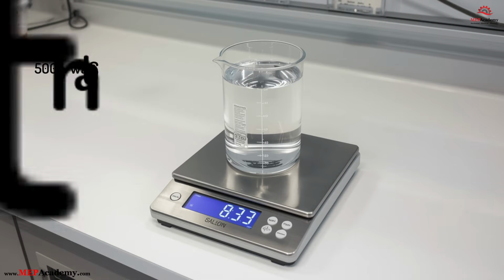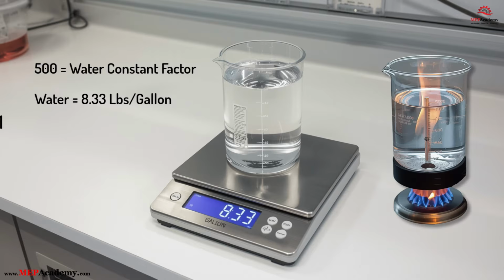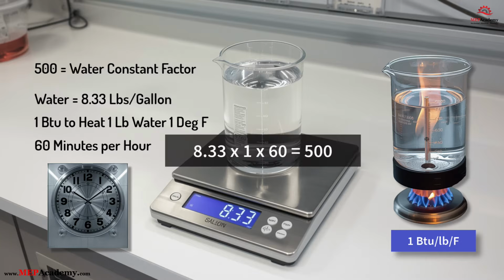Why the constant is 500? Let's quickly explain where the number 500 comes from. Water weighs 8.33 pounds per gallon. It takes 1 BTU to heat 1 pound of water by 1 degree Fahrenheit. There are 60 minutes in an hour. Multiply those together: 8.33 times 1 times 60 is approximately 500. That's why this constant works across all hydronic systems that use plain water.